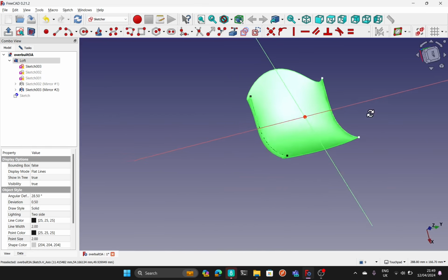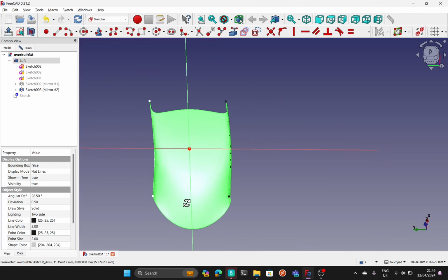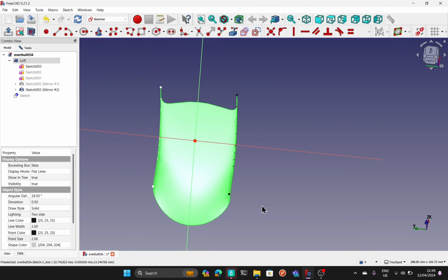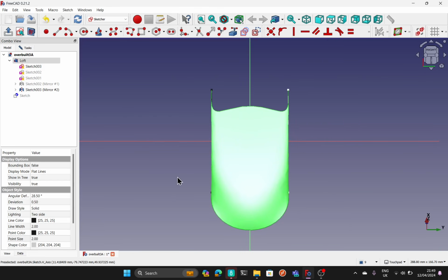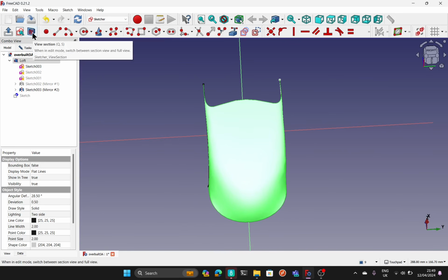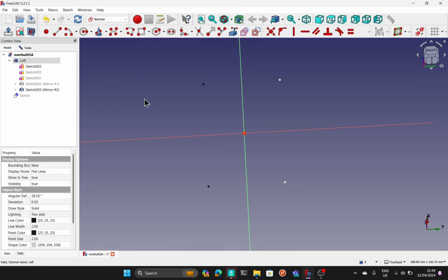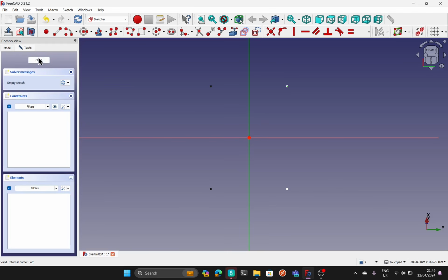Trouble is, now I've changed my viewpoint, how do I get back to basically this viewpoint here, where it's something like this? Well, the easiest way is to come up to the top and we have this sketch with a magnifying glass. I click that, we're basically back to where we were when we entered the sketch. You can see, well, we're around the wrong side. I could either use a section view, cut through that, hit that icon, and I can create my sketch upon here. Or I could come out, go to the task, hit close.